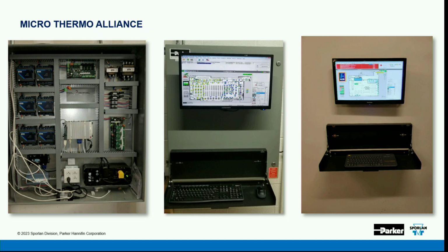It does it automatically. Now, let's just say that somebody was working overnight and they temporarily killed the power in aisle 12 and then said, oops, turned it back on. You might miss those few nodes there, but there's going to be a report on the screen for you, and it's going to tell you that those nodes got interrupted and you have to just service pin them again. So it won't let you leave something unprogrammed. But you don't have to sit there and watch every node load. If you do the delayed install, it'll do it overnight by itself, and then you'll get a status report. Open up the status report and see if it was successful.